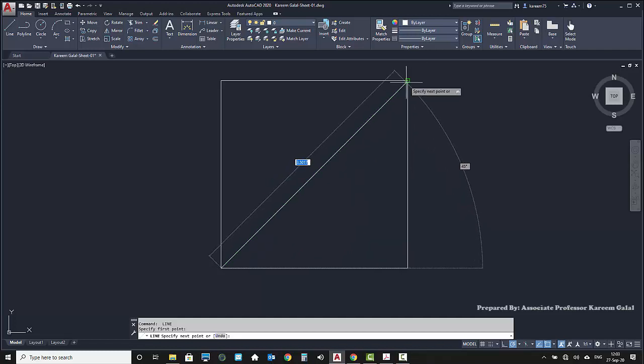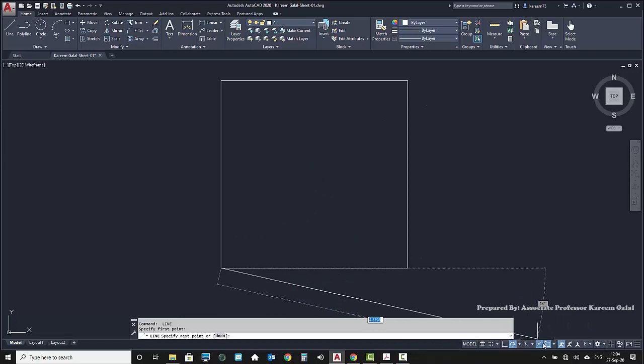We can see a small green square annotated with Endpoint. This tool is called the Object Snap tool. The OSnap tool helps us to draw accurately and find exact endpoints, midpoints, center points, etc. We can activate or deactivate it from its icon or with the F3 key. To customize it, you can browse the options through the next arrow.